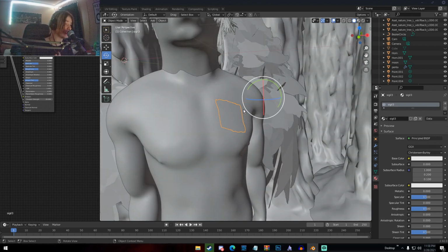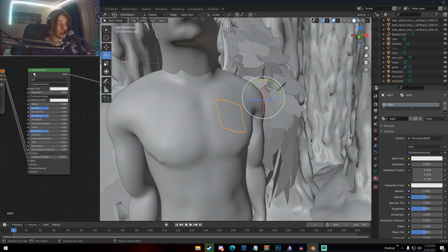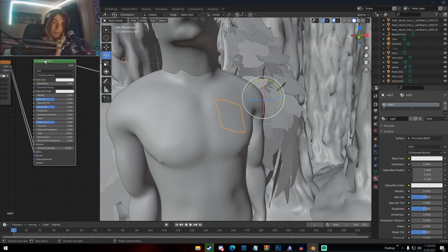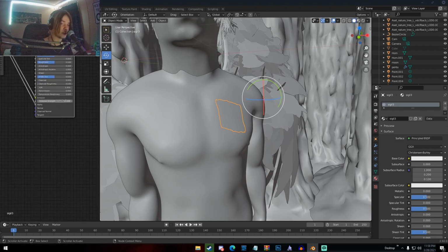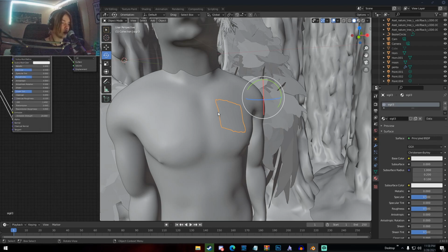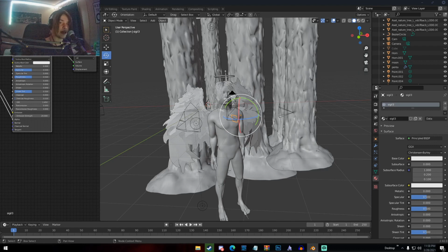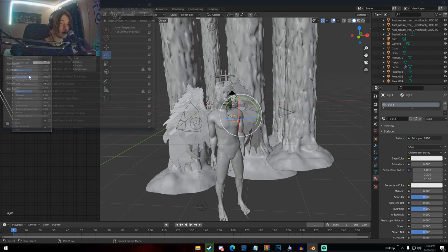Basically all this is literally an image that I've imported in Blender with an emission shader. It's not an emission shader, it's a principled shader, but you can see the alpha of it is put into the alpha because it does have transparency, and the color is put into the emission, and the emission strength is on 20.